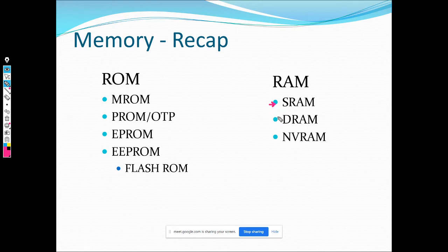Now coming to DRAM, which is dynamic RAM. It's called dynamic because it has to be dynamically refreshed. In DRAM there is only one transistor and one capacitor. Based on the charge of the capacitor, you will know whether the DRAM holds bit 0 or 1. The downside is that the capacitor's charge decays over time. If you take a capacitor, the characteristic is going to be like this, and this is time, and this is going to be your charge, q.